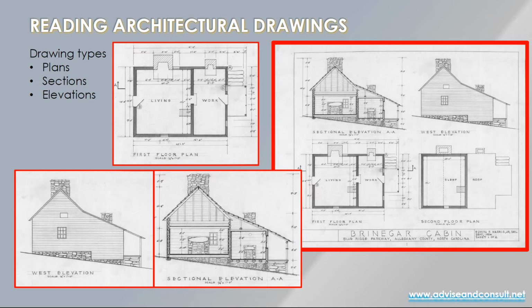Typically the furthest away is the larger aggregated dimensions that refer to larger components of the building or the detail or the section, whatever it is. And then smaller, the next string in breaks those large dimensions down into smaller specifics of the particular building or space.